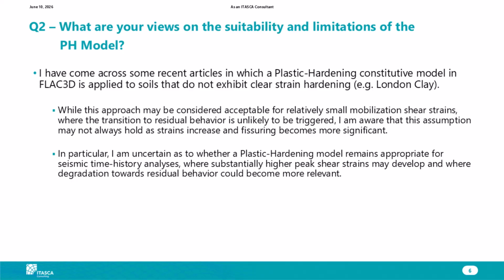And so that in static condition is fine. I never tested and used it. It might work even in dynamic, but I never tested and used it in dynamic. I've used the traditional, I would say, the standard formulation of the plastic hardening in dynamic, when there is no liquefaction. If there is liquefaction involved, I wouldn't use it. There are more elaborate, specific models for capturing the liquefaction triggering and also the post-liquefaction aspect, like the P2P sand or the North sand and similar.